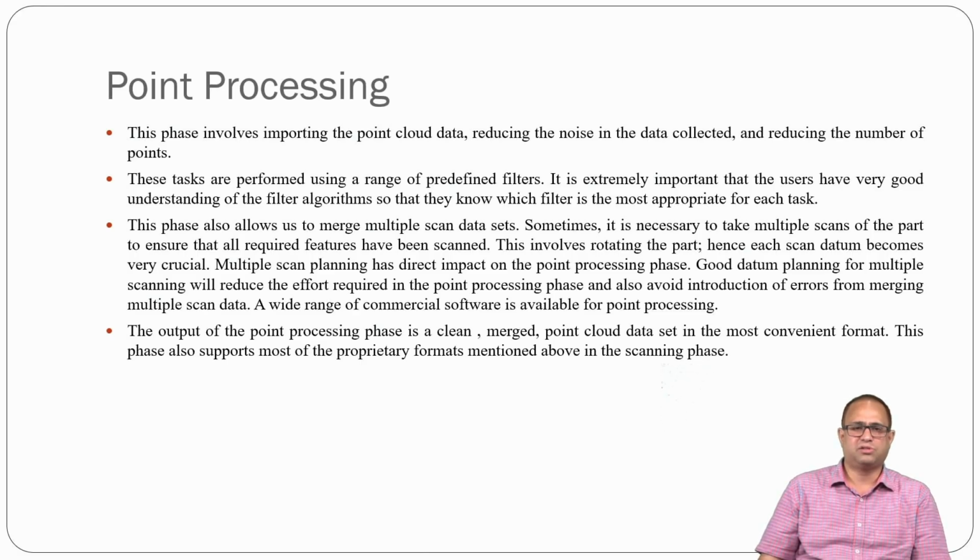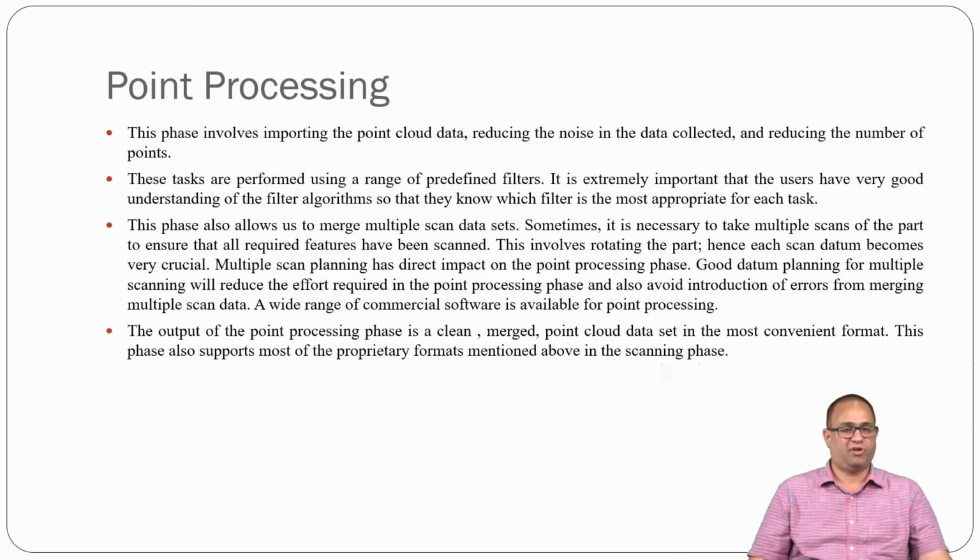This phase also allows us to merge multiple scan data, and this multiple scan planning has a direct impact on the point processing phase. So good data planning for multiple scan data is required, which is going to reduce the time required to do the point processing. The output of the point processing phase is a clean merged point cloud data set to the most convenient format, and then that format is going to be used for CAD/CAM CAE software.